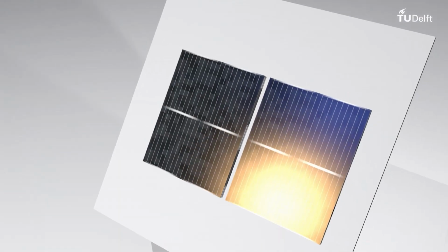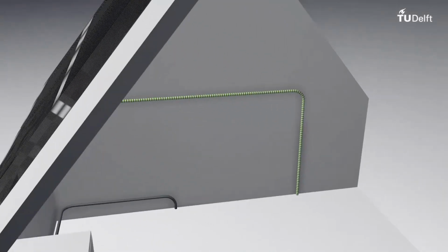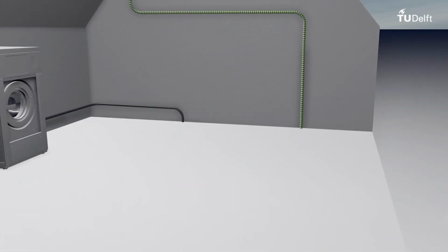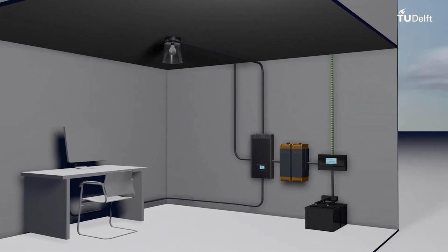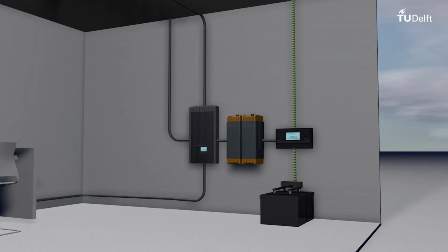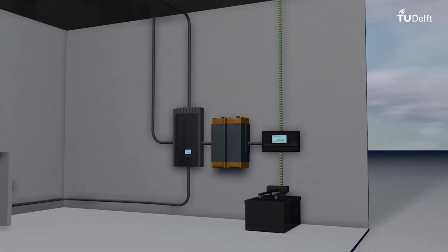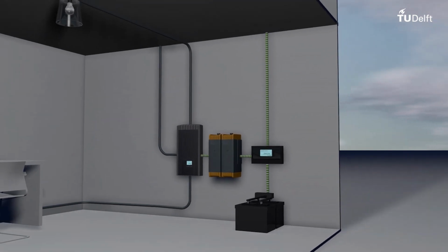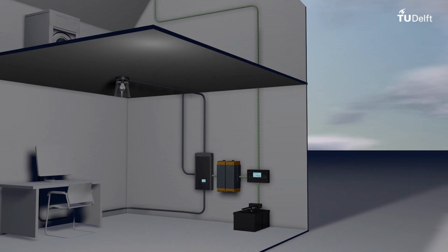On a normal day with the sun out, the PV modules on top of this rooftop are busy converting the incoming irradiance into photo-generated power. The battery is constantly being charged or discharged through the charge controller depending on the different PV supply and load demand. The off-grid or standalone inverter is continuously converting the DC power to AC and supplying this AC power to